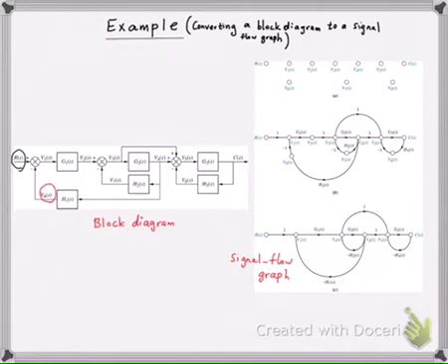and V1, you see that in order to reach from V6 to V1, you have to invert the sign of V6. So if there is a way to represent the relation between V6 and V1 as a transfer function, that transfer function is just going to equal -1, and that's exactly what you see here.